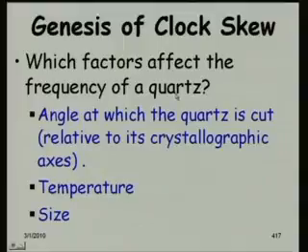Okay, so the reason is that it has elastic property, right? It is one of the, and also it is not a good conductor of temperature. Otherwise, temperature will very largely affect its frequency. If it is steel or something, its frequency will largely be determined by temperature, even though steel is also elastic. So, quartz is an elastic material. Even if it gets disturbed a small amount, it will return to its original shape, and also it is not a good conductor of temperature.